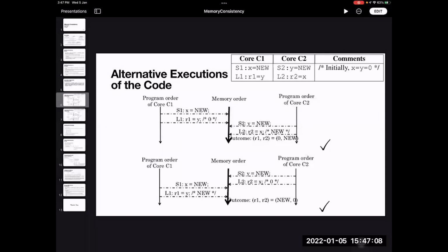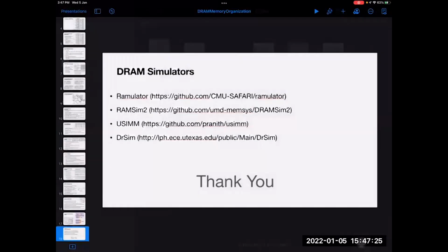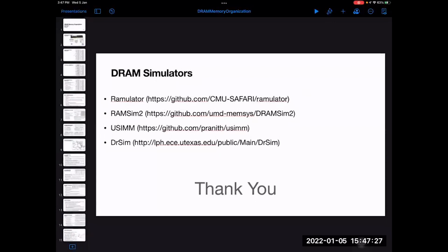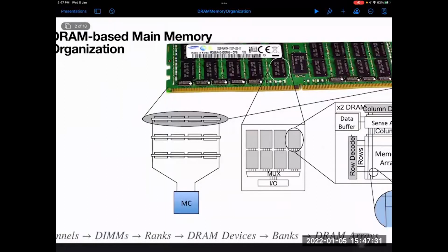But these are required if you are considering the memory for a server type of systems. If you are considering a laptop and low-end systems and so on, generally DIMMs may not have the ECC capability. I'll just go back to this DRAM memory. I'll just show you one thing. So for example, if you see here, this is an ECC based memory.